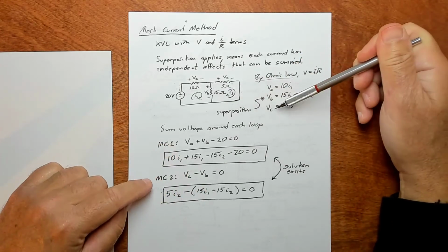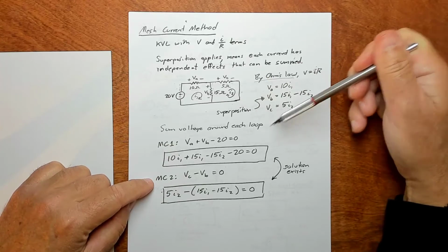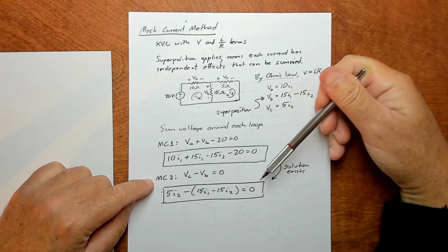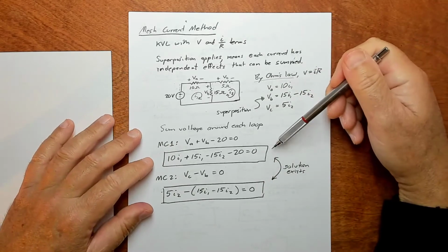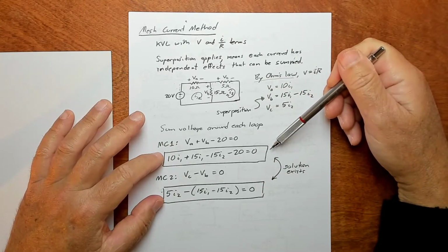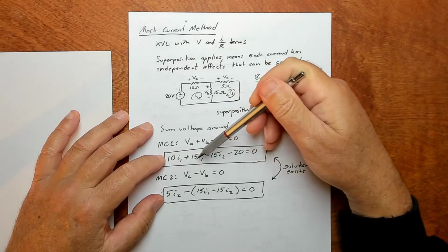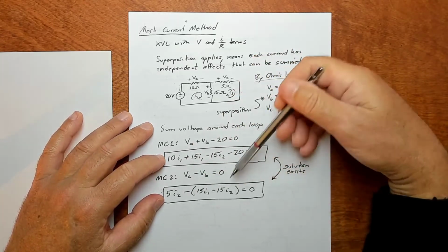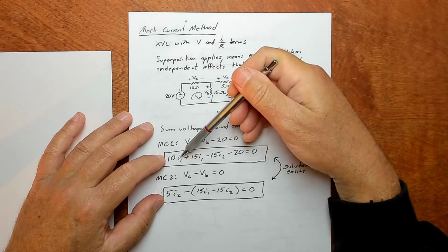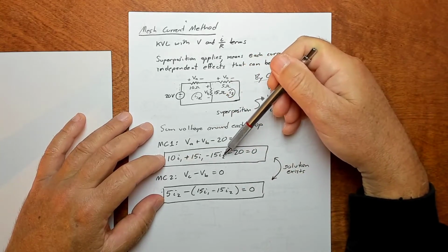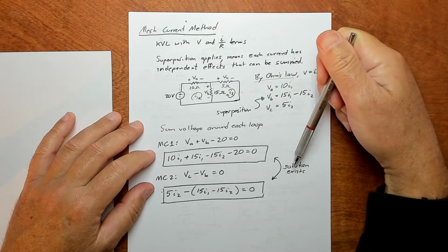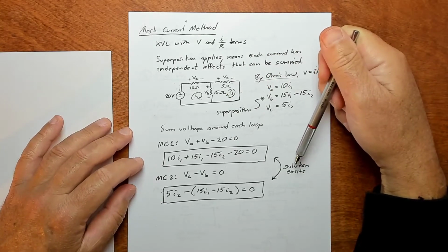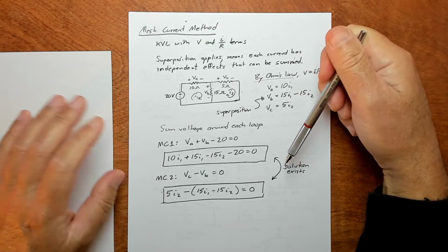Then once again, substitute these two equations in here, and you get this thing. So what we have is two equations that are in terms of i's now, right? There's two equations and two unknowns, I1 and I2. So once again, there's a solution that we can solve by various methods, and we'll use the matrix method most of the time. So that's the methodology.